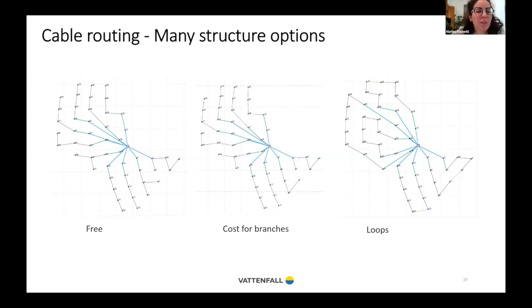So a lot of the time in the company, they were pushing for what they call a string layout. So a layout where there was only one turbine connected to one turbine and no branches. So we have a version of the software that does that. You can impose to only have strings and you can compare the costs. You can also do more. And this is what we see in the middle, you can quantify what would be the cost of having branches, then give this as input to our optimizer that will optimize based on also this cost and suggest you a layout.